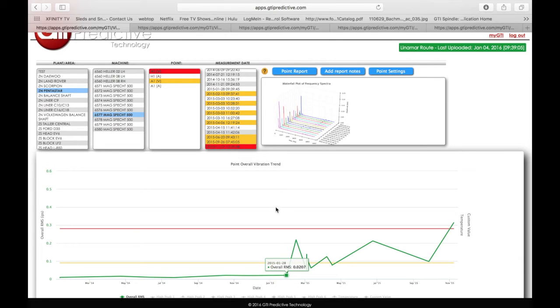Number one, if it's not the tool and it's the spindle itself, we can correct it by pulling out our balancing app and correcting that asset point. But being this is a spindle and knowing that this is probably a tooling issue, this is something that we can address with the tooling department.